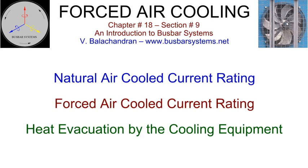The sizing can be carried out for the following constraints if specified. Forced air-cooled rating of the bus. Natural air-cooled rating of the bus, should the forced air cooling equipment fail to operate. Ability to meet the specified temperature rise constraint at rated current for the failure of the cooling equipment for a specified duration of time. Evidently, the time duration has a limiting value depending upon the time constant of the isolated phase bus.